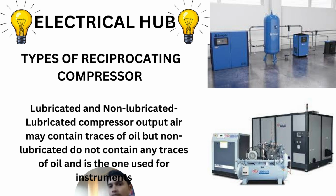Lubricated and non-lubricated. The output of lubricated compressors may contain traces of oil, which generally doesn't happen, but it is considered that it contains a fraction of oil. So they are basically not used for instruments. For instruments, the non-lubricated compressor is preferred.